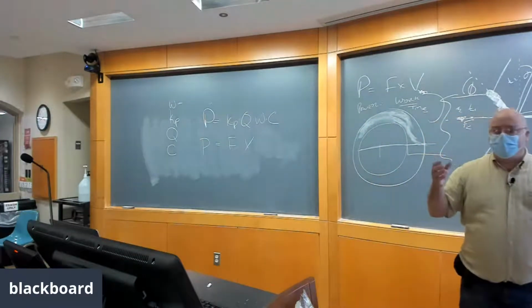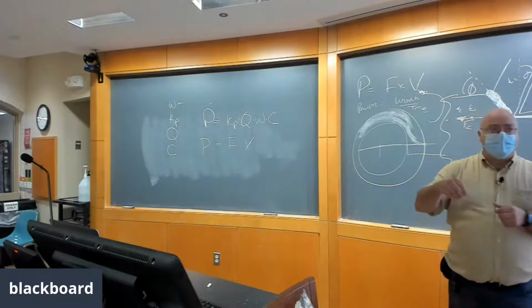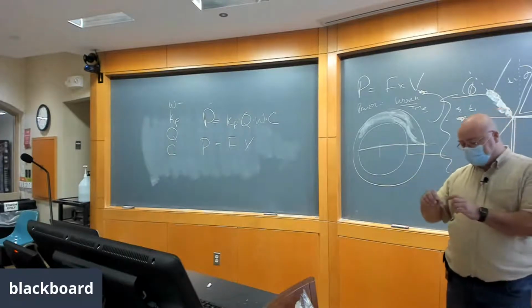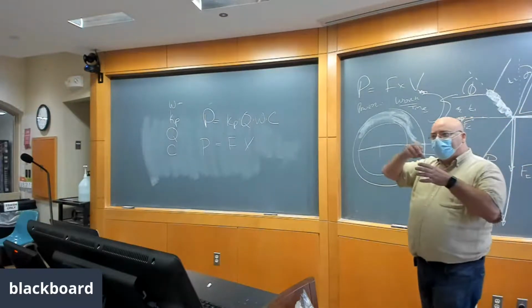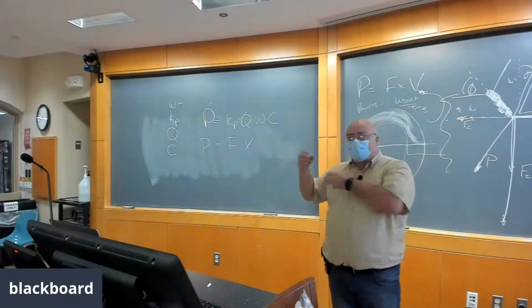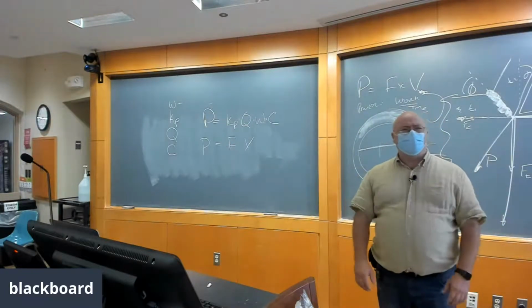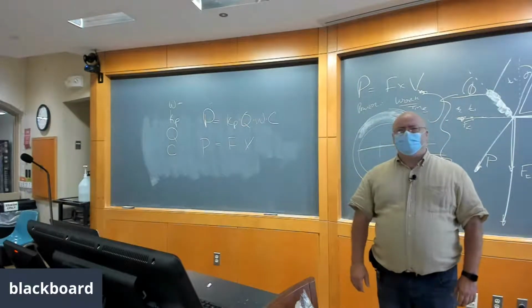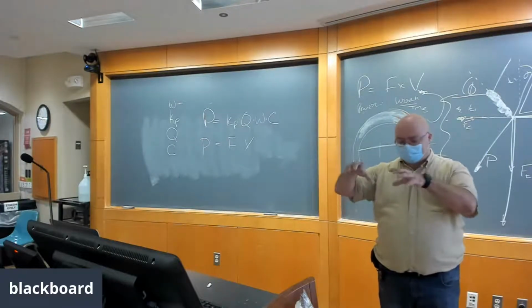Yeah. And so one of the ways they do this is they cut for a little bit, and then they take the tool out and they look at it in a microscope. Then they cut for a little bit and they take the tool out and they look at it in a microscope. Then they cut for a little bit, right? And so you build up this pattern of how quickly the material on the surface of the tool wears out. We actually did, I think it was an MQP. Nah, I think it was a kid working on a master's thesis. I can't remember exactly which one it was, but it was similar to that.